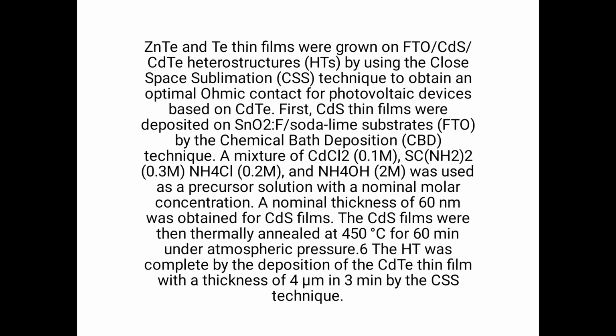First, CdS films were deposited on SnO2 FTO substrates by the chemical bath deposition technique. A mixture of CdCl2 aqueous solution with a nominal molar concentration was used, and a nominal thickness of 60 nanometers was obtained for CdS films. The CdS films were then thermally annealed at 450 degrees Celsius for 60 minutes under atmospheric pressure.